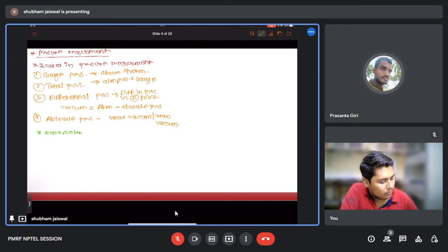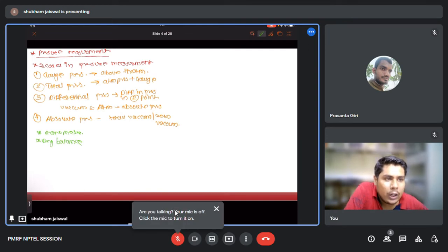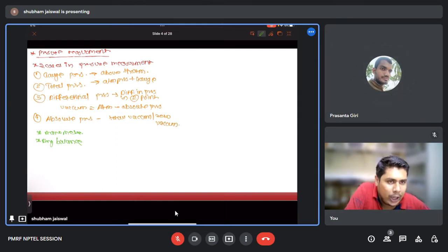Okay, so we have seen the manometer, then we have seen the ring balance. Depending on the application, when we need to measure the pressure inside a bicycle tire or motorcycle tire, we can use the Bourdon tube, because accuracy does not matter that much. But in process control, where we need to measure the pressure, we need the most accurate one, like the electric pressure transducer. There are also different types, which I will also explain.